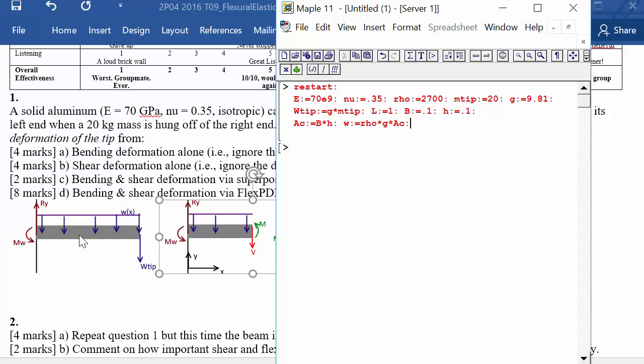Okay, that's not the only way to do it. You could look at the effect that this distributed load should have. It should be the same as the total weight, just applied at the center, as far as what it creates in terms of reactions, but it's not going to be the same for the internal shear force. So we better keep it all spread out while we're looking for what that internal shear force and bending moment is. Okay, so there's W.